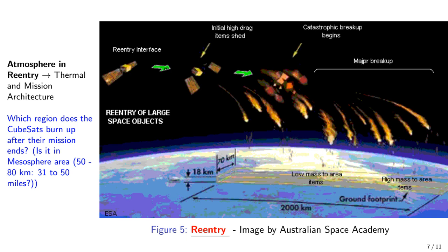Okay. So let's now read that together. It says the re-entry process. Uncontrolled re-entries are always at very low grazing angles, less than 1 degree. The re-entry object is traveling at about 8 kilometers per second down to below 8 kilometer altitude. Break up, that's the question I asked now. Break up starts at around 78 kilometer altitude. And what is 78 kilometer altitude?